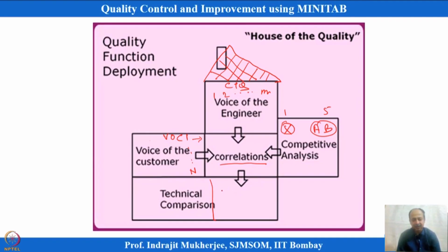So, in this case what we can see in this box is the technical evaluation on every CTQ. So, all the CTQs and the evaluation on a scale of 1 to 5 again. Okay. So, where we stand as compared to the CTQ provided by the competitor. This information may be used in reverse engineering. When we are doing reverse engineering, this information will be useful over here. So, the voice of the customer will be translated into CTQ dimensions over here. Okay.